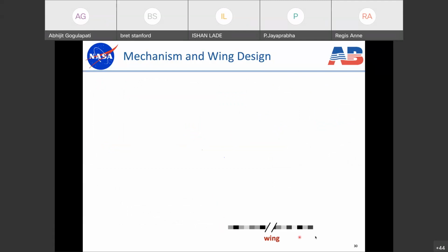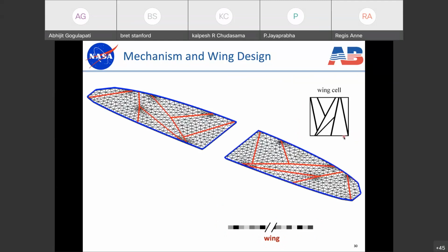We have a set of division rules, which is shown here. These are the vector of real numbers, which are our design variables, and we use these to define the wing. And so we can pretend that this set of division rules creates a cell structure that looks like this, for example. And this is just a random cell structure that we came up with. And then we can take this cell structure and map it onto our wing, and we get this. So hopefully you're able to visually understand how we would extrapolate this into the planform shape, and you get this structure here.